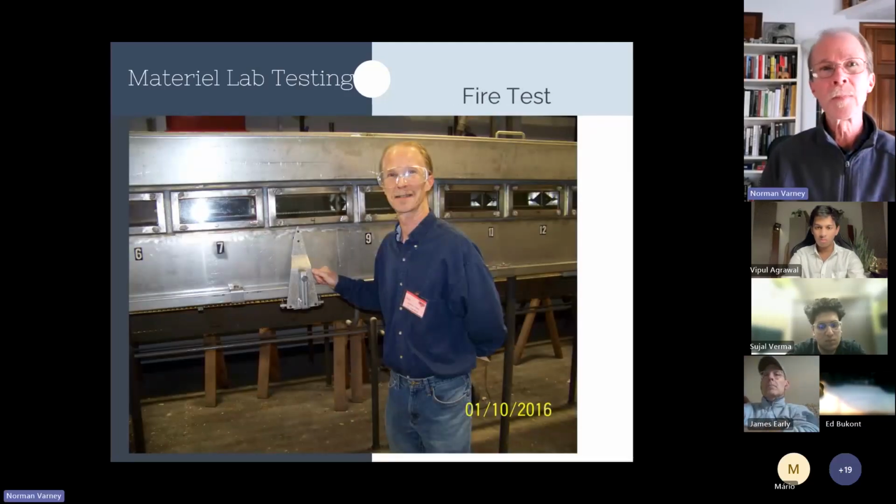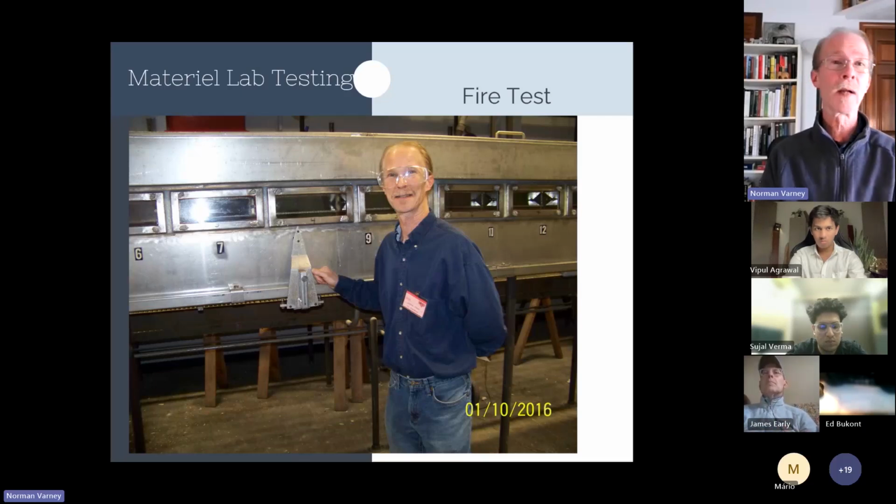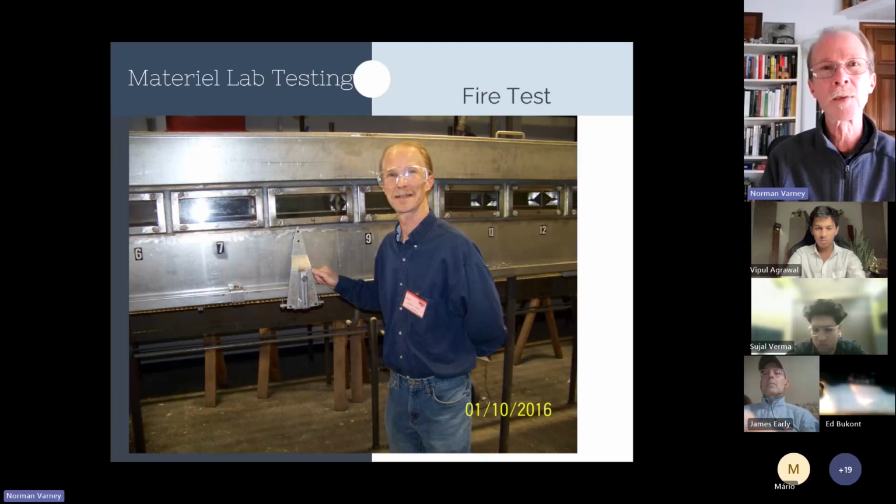And then also, these products have to be fire rated. If they're going to go into a commercial or residential facility, you've got to know, and in fact there are codes, especially in the States, where it is a requirement. This has to be Class A rated, or pass the California corner burn test. This is a product that I was working on, our constrained layer damping material.